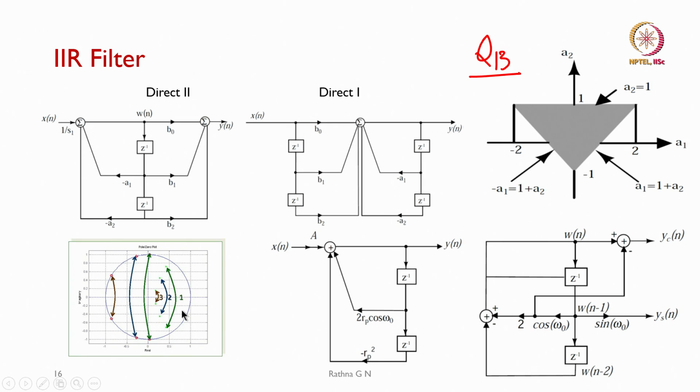And we said how you are going to combine them. Most of the time we have the complex conjugate poles, and zeros will also be occurring. How we can combine them: the pole which is farthest is combined with the zero nearest to it, and so on, so that any disturbance is going to be minimized.